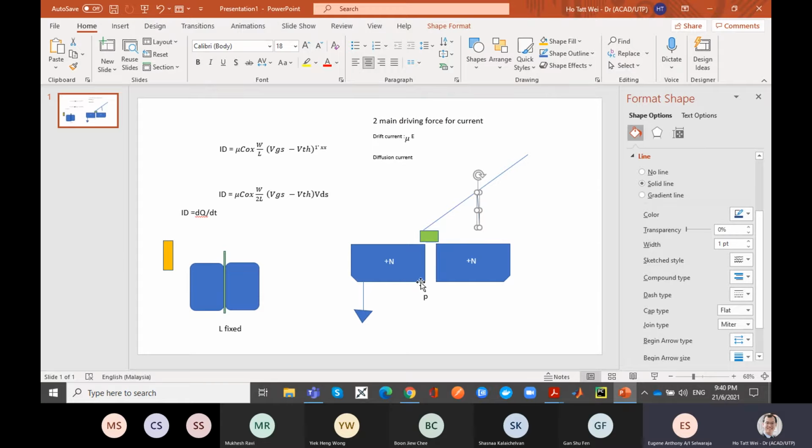Transistor. Specifically a bipolar junction transistor, right? Which is basically like joining two diodes in opposite directions. Okay, this is a transistor, but this is a field effect transistor. Why? Because you are having an electric field giving it an effect so that you can form a conductive path. That's why it's called a FET, field effect transistor. MOSFET, metal oxide semiconductor. This is metal. There's an oxide layer here and there's semiconductor here. Metal oxide semiconductor field effect transistor, MOSFET.